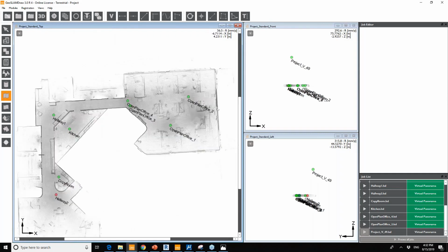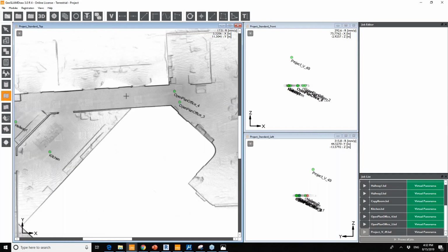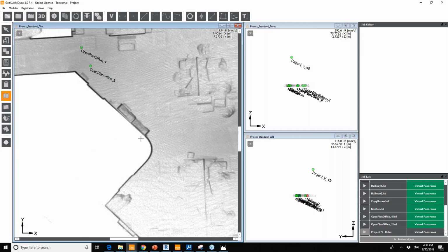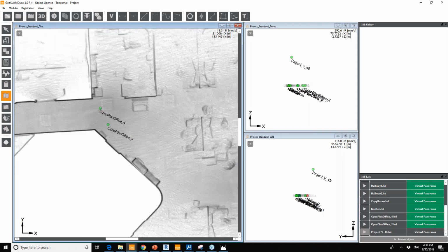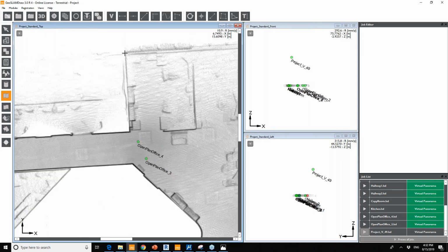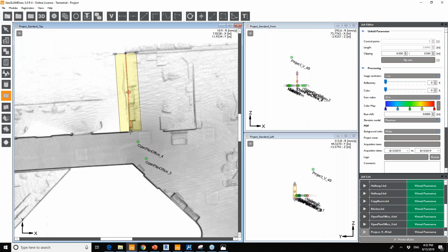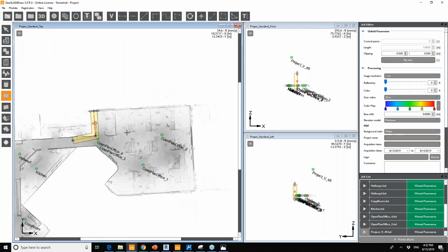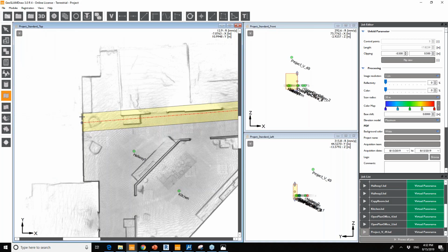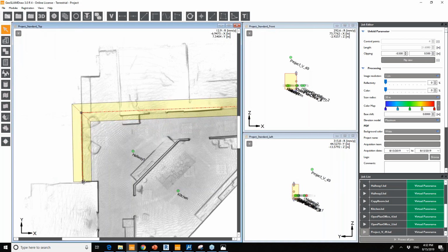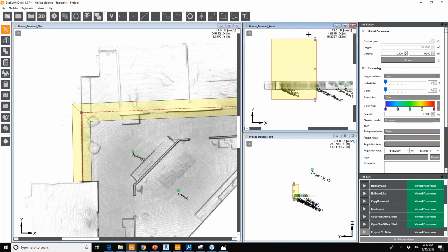So for instance, using the office building, over here, double click to finish. You have options to adjust the clipping area to make it wider or more narrow, and adjust it on the front or side view as well. Make sure that the entire building is included.